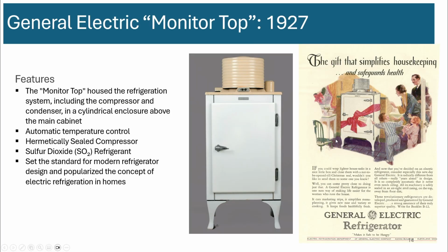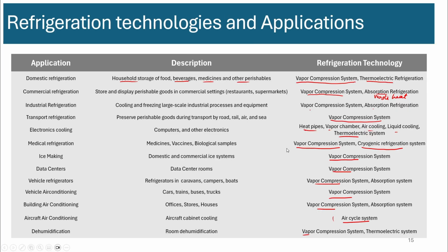And aircraft is a specific example where that is practical, even though it's extremely energy inefficient. But other safety and convenience constraints make this a better option over vapor compression systems, because such vapor compression systems would create a much heavier load for the aircraft, in addition to creating additional safety constraints.